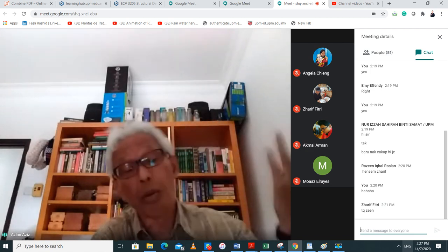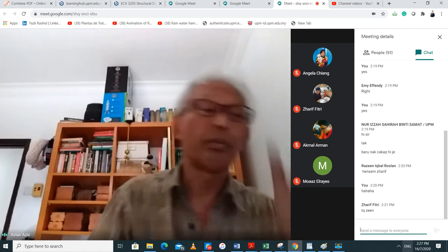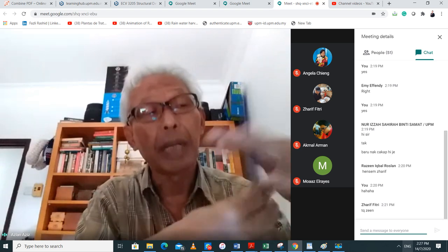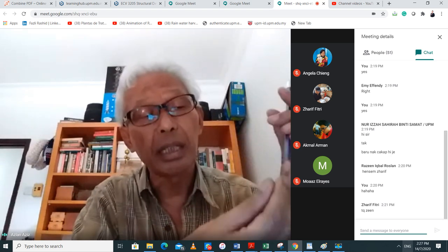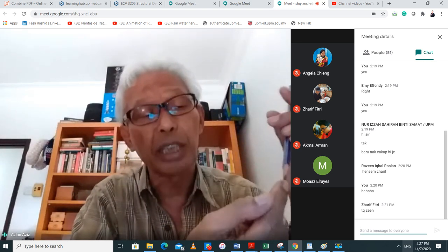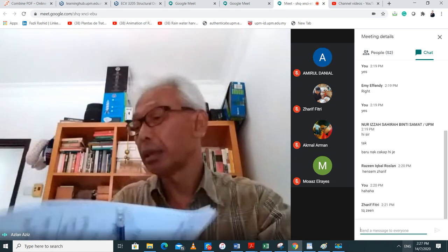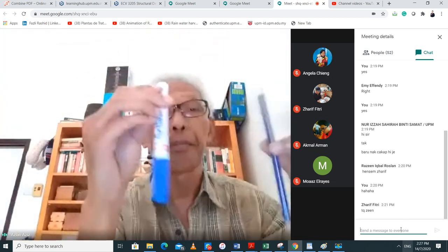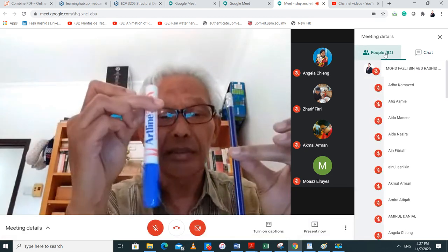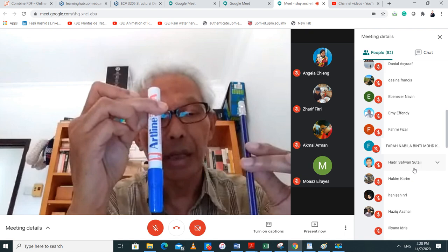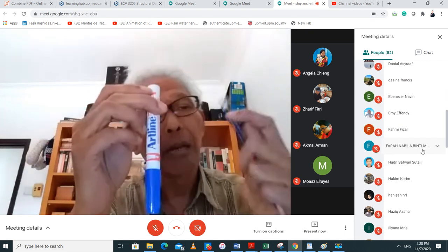Now the other component was the shaft friction of the pile multiplied by the surface area, and the first part was the tip resistance multiplied by the area of the pile. All right, here's my pile, here's my penetrometer. Here are the things that we're talking about. So whatever comes out of the penetrometer at the tip is the same as the pile. Now the other part is the shaft.